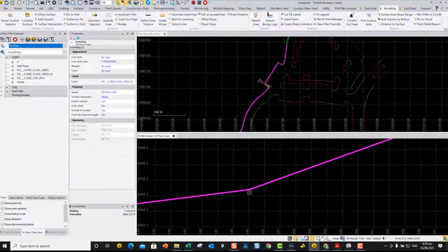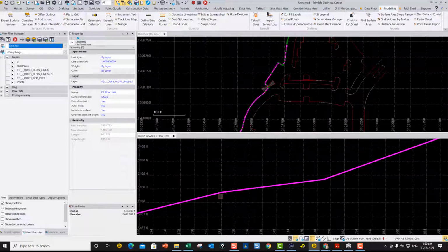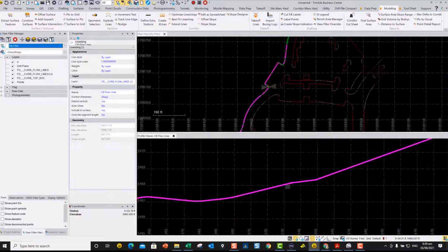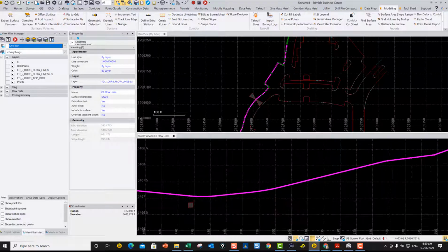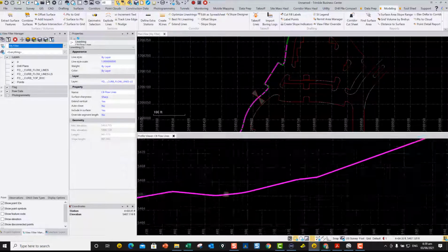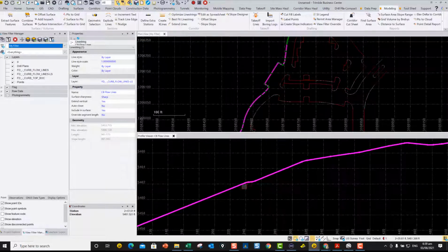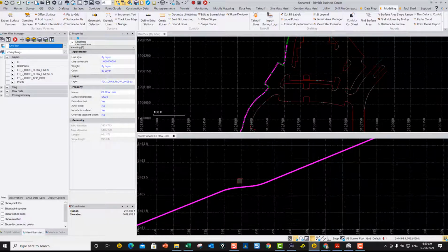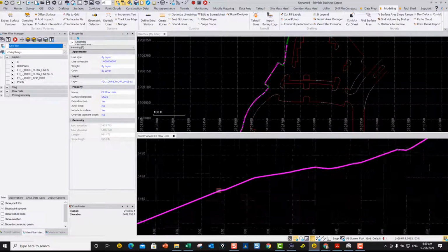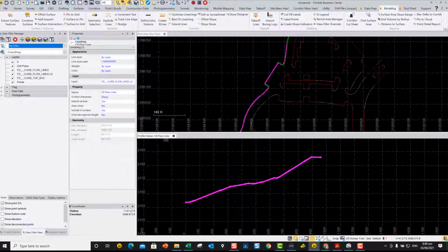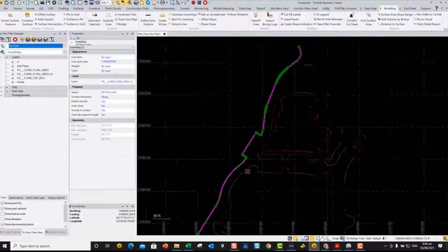At the other end, that's the angle break, but over here on the rounded corner, it's rounded it off, and within 200ths, it's making a nice smooth curvilinear line, which will look a lot nicer in the parking lot and give a much nicer fit and ride to the parking area as well. So here you can see there's a bit of a switchback curve, and it's fitted that nicely as well. So each of these lines is now ready for use in a paving machine.